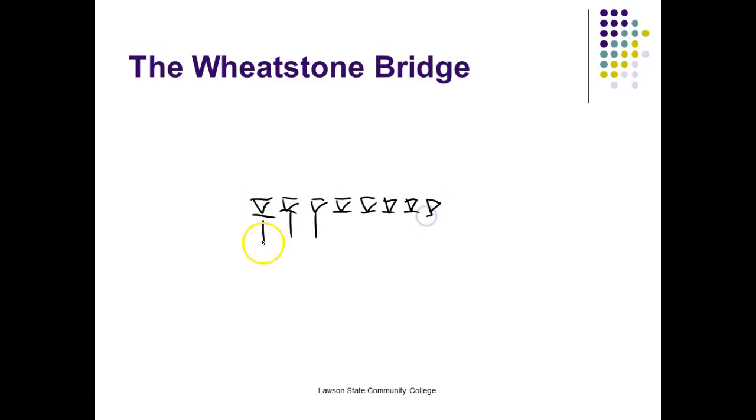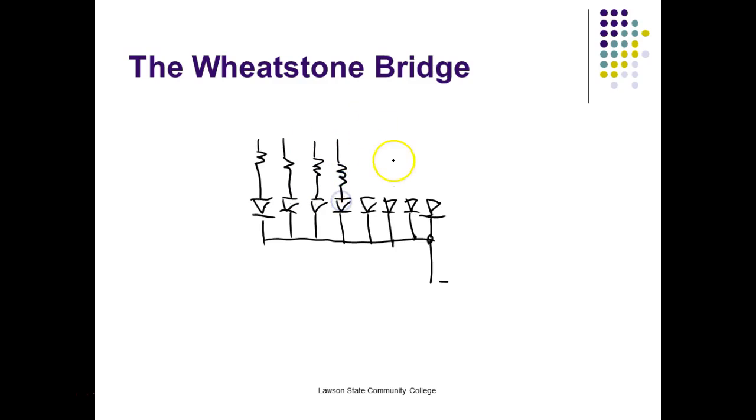This would be the cathodes. And inside, these would all be tied together. And then they'll bring out 1 or 2 pins right here. Now, what would we connect this to? Well, we would connect this to the minus. Right? You understand that? So what would we turn these things on with? Well, we would turn them on with a voltage, right? If it was over 2 volts, then we would have to put a resistor in each one of these. I'm sorry, my resistors are looking like inductors.